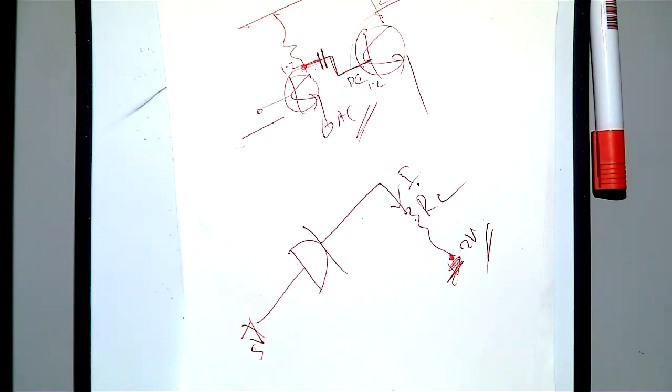So in order to avoid this cascading issue, the requirement of higher DC voltage, people came up with, why don't you put a PNP transistor here, amplifier. If you put a PNP amplifier, actually you can have less voltage here, because this is the base, this is a PNP. In order to make a PNP on, it's not VBE, it is VEB. And then your base can have lesser voltage than your emitter. So that is the reason we are using PNP. When you are using PNP, this voltage can be very small, 0.4 volt, depending upon how much resistance you connect. By using a complementary device, that is a PNP, active level shifting can be combined with amplification.